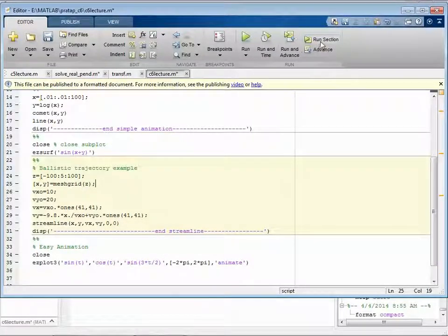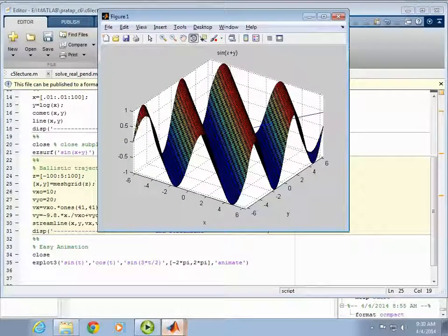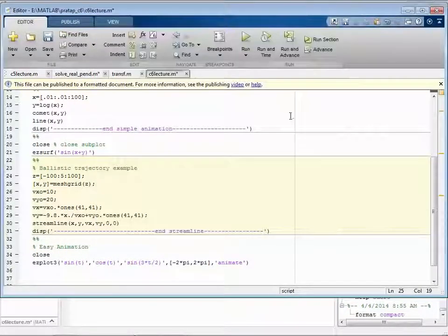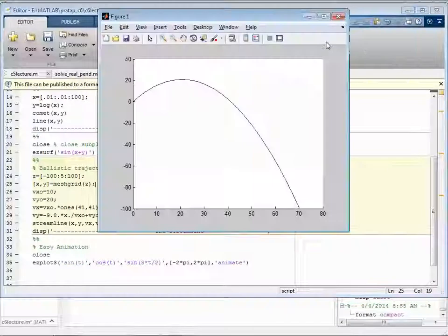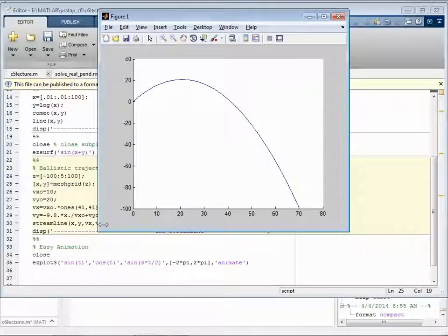Okay, boom. Let's take a look, see what it looks like. Look, there it is, it crossed it. So I'm going to close out the figure window and just redo it. There we go. That happens sometimes. Some of these algorithms will just keep adding to the previous figure. You don't even have to type hold on, but they do it anyway. Streamline is one of them. So you've got to watch out for that a little bit. You noticed that, right? We created a 3D plot, and then Streamline just added over it.